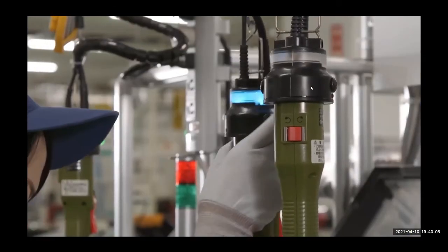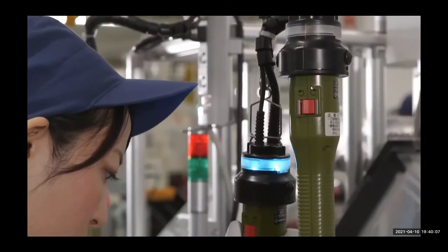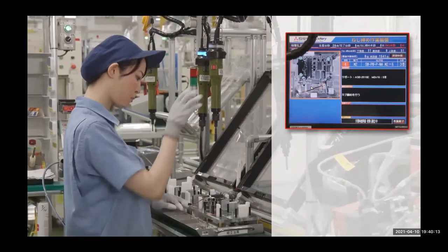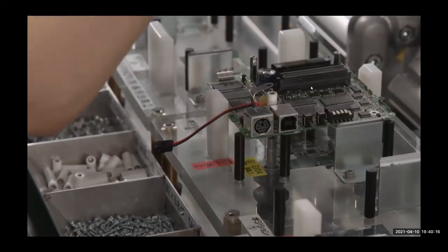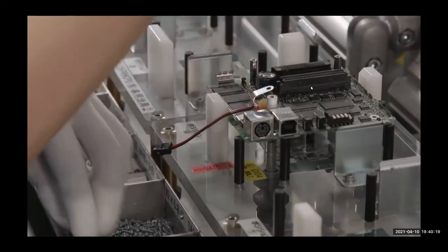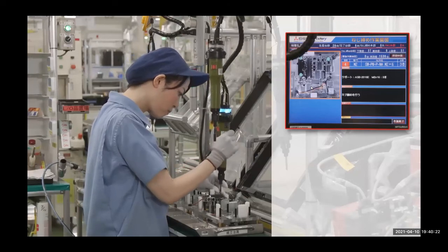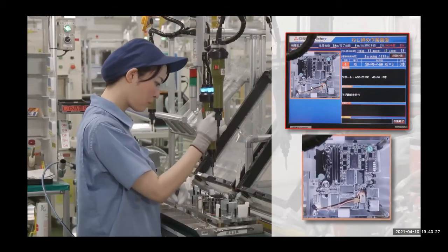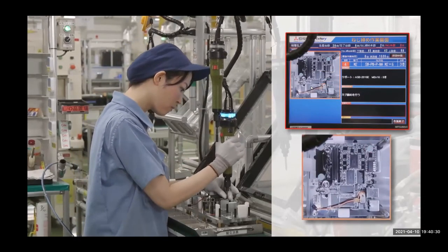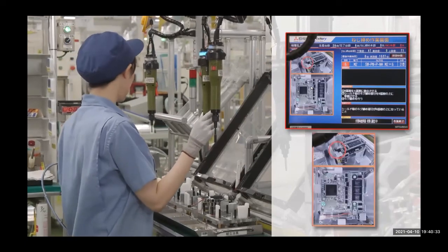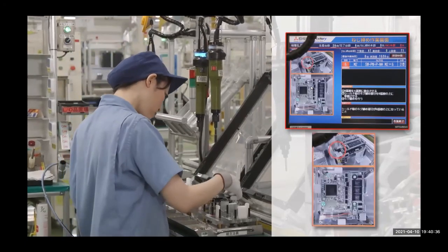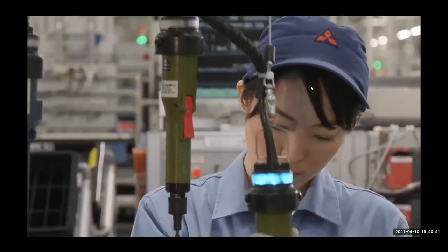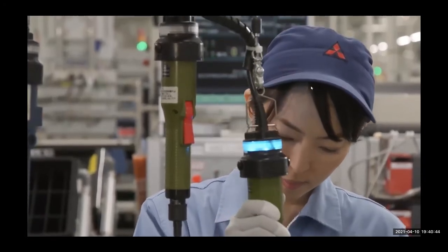The LED lamp lights up to indicate the next screwdriver to be used. The worker can accurately take out screws and select the next screwdriver without checking the job instruction. The indicator displays the screw tightening position and tightening order. The color of the tightened screws changes on the display so that the next screw tightening position can be checked at a glance. In addition to instructing the work procedures, the system can automatically determine the quality of screw tightening by using the sensor installed in the back of the screwdriver.